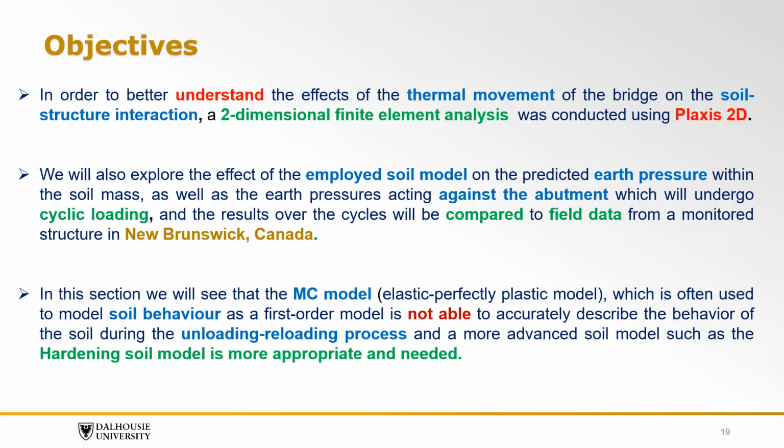And also in this section, we're going to demonstrate that the simple Mohr-Coulomb, or elastically perfectly plastic, soil model that is frequently used by several engineers to model such a problem is not good, and it will not accurately describe the behavior. It will not be able to do this. We need more advanced soil models, like the hardening soil model, to be used.